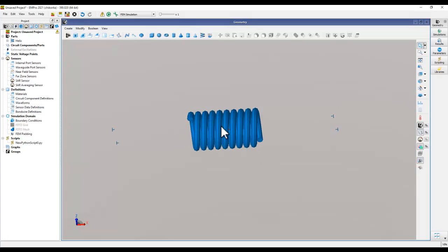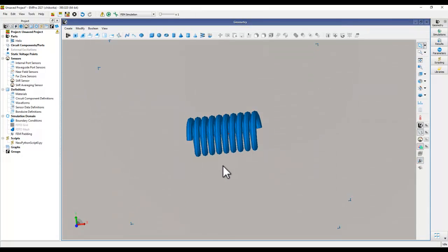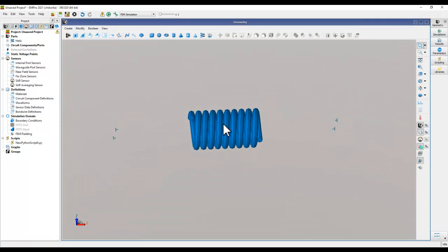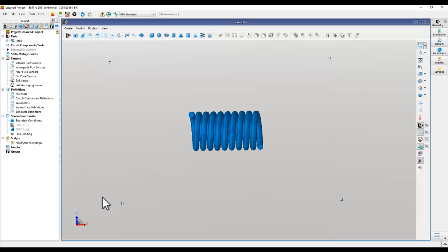So that means this helix, while it is forming the basic coil, I still need to extend it to the X axis and then attach the mounting pad, which we will solder on the PCB. So this model is not fully complete, it's a little incomplete. Another thing you notice when I look at X and Y and keep the Z axis on the top, the coil is ending here and this side is ending here.